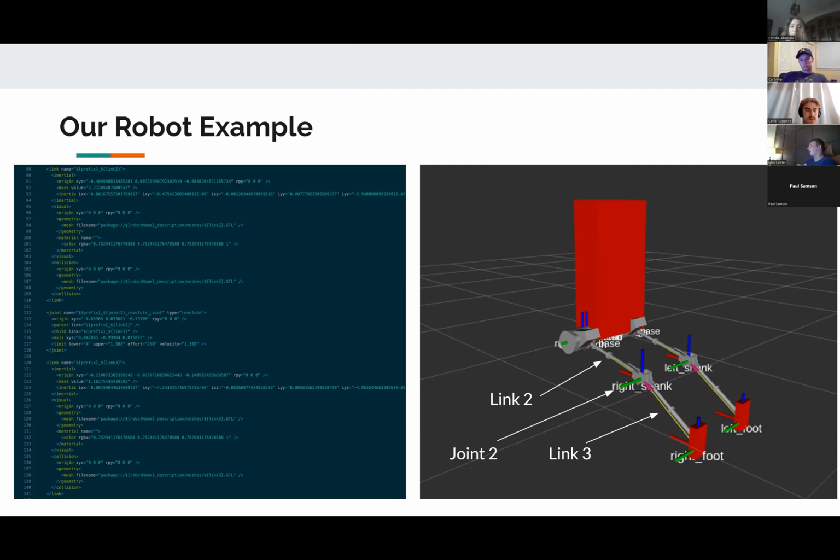When we were talking about getting those smoother cylinders, that was more for the sake of figuring out some of our physical parameters, like the inertial tensors, because you can imagine the difficulty of finding the inertia of something with a million different little divots and points. It's a very difficult shape to work with. So in order to simulate, we really just need an approximation, and that's where those cylinders come into play.